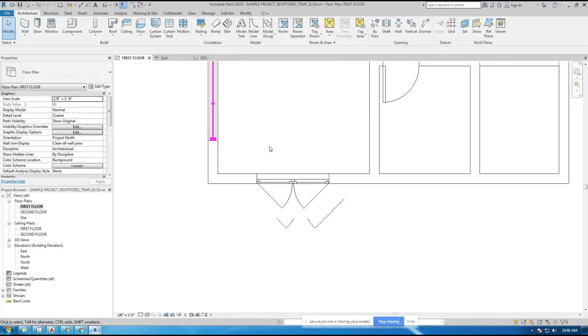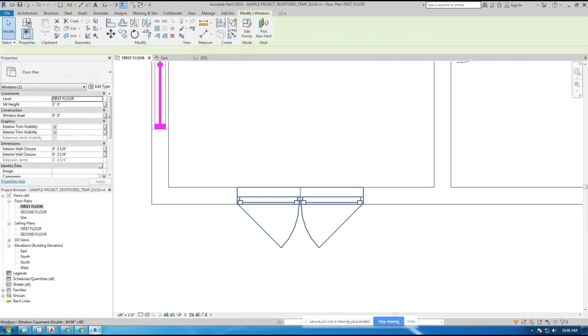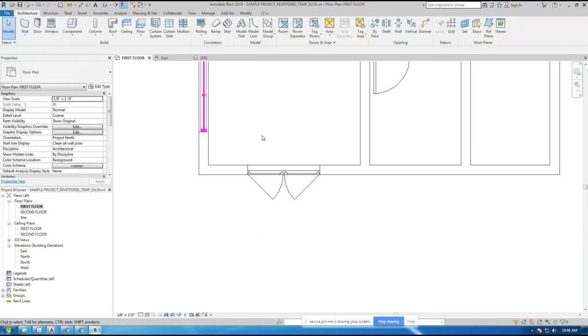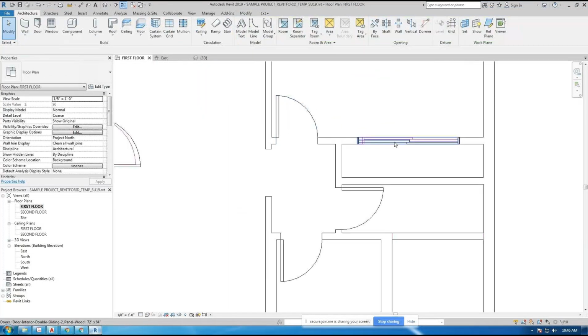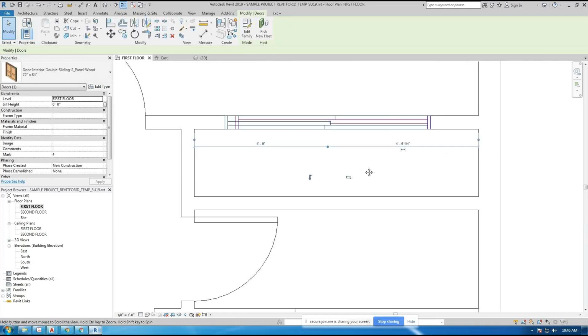There was a quick question about witness lines. When you click on an object and it launches its dimension settings, like for example here, the witness line is that little dot right there. See, it says move witness line. That little dot at the end of a temporary dimension can rubber band or jump to different places. It'll jump from left to right to center.